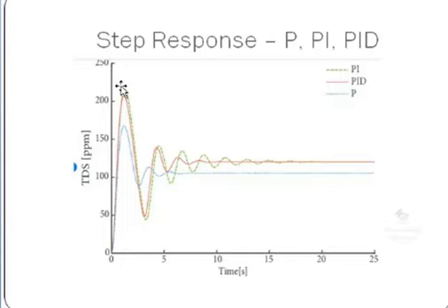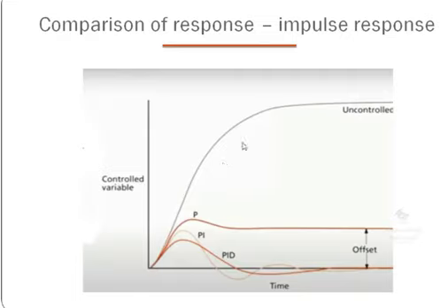So to reduce the overshoot, I am introducing PID. Red color. What has happened? The overshoot reduced, but still there is scope for improvement. Okay, overshoot is reduced and it is reaching the set point after the green color. So it will be more clarified with this slide.